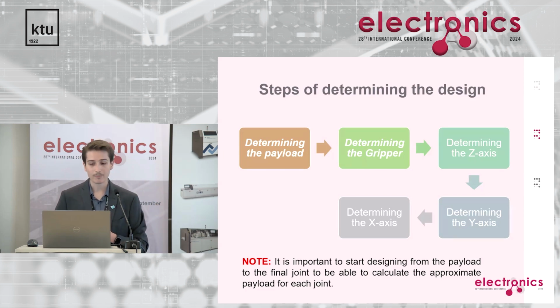As I mentioned, this project is about a Cartesian coordinate system, a Cartesian robot. There will be a figure about this one. So we have 3 prismatic joints. We have 3 prismatic axes. The z-axis is an electropneumatic axis, which can go up and down. In this case, we have a y-axis and an x-axis. Y and x-axis, it's very important. They are electro-servo drives. So in this case, we are focusing on the drives as well.